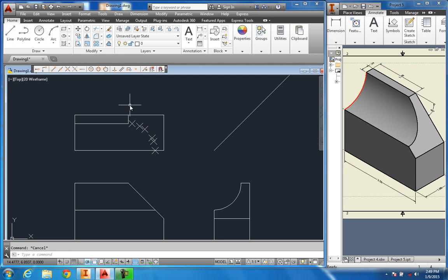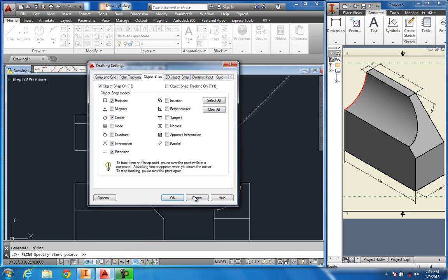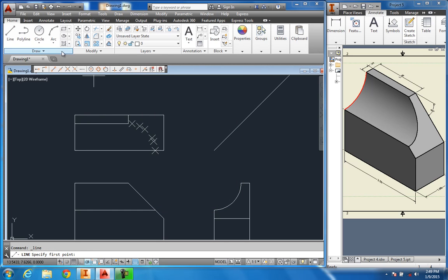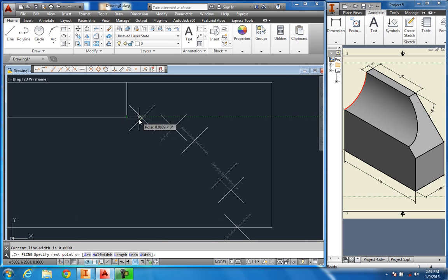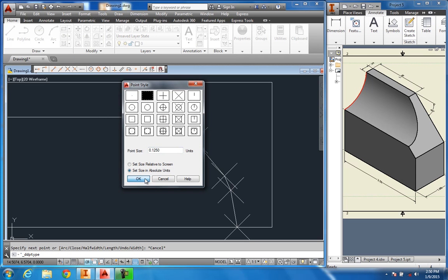And to put that plotted curve together, what I do is I come up here and hit polyline, click on it, and when you're using your object snaps here, make sure your node is turned on. You can also come down here into your object snap, hit settings, turn on the node button, okay, and basically hit your line or polyline, start right there, grab those nodes down through here, just like that. Come back up to format, point style, and we'll turn that point style off.